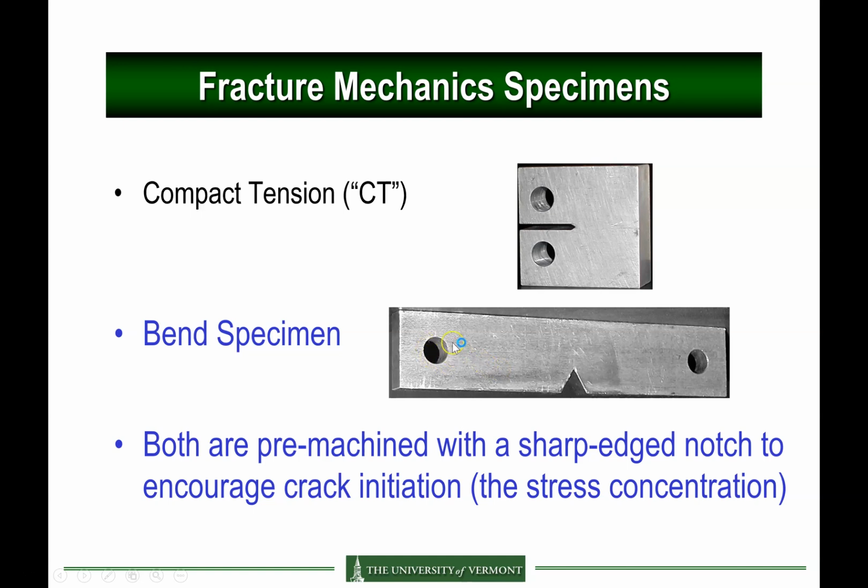So you'll have attachment on both sides, and the notch is at the bottom. And usually what we will do here is a 3-point bending. So it will be attached here, and a wedge will press on the opposite side of the notch to propagate a crack here.